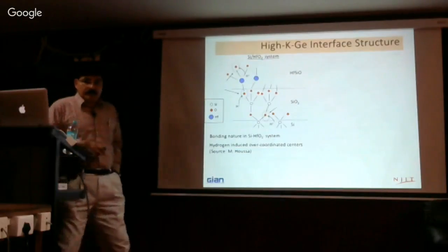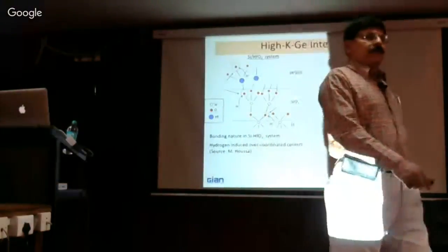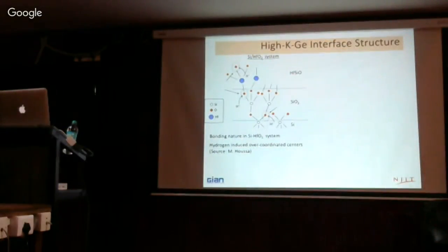Pardon? The threshold voltage will be affected by the interface charge as well as the bulk charge, because bulk charge will change your Qss. That's why the threshold voltage will change. A bulk charge is created, but not an interface charge, and it will reduce the threshold voltage. The interface charge can reduce or increase it, depending on the type of charge formation. You understand? If we have negative charge, it will actually increase; if you have positive charge, it will decrease. That's the way the flat band voltage will sit.